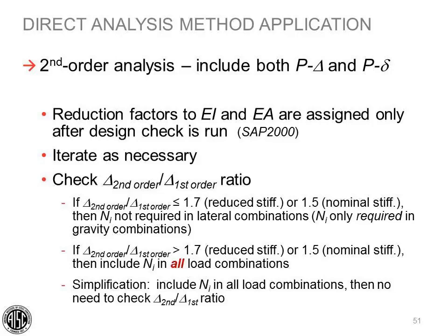Okay, thank you. The next question. The industry that I work in still uses ASD, the 9th edition specification. We're currently discussing changes to include P delta. Can you clarify how this will not create a more conservative design? For a flexible system, the P delta effects will definitely increase the demands on the structure.